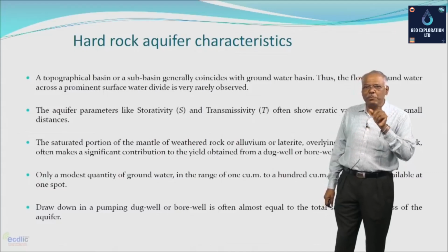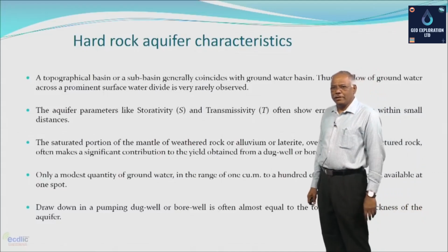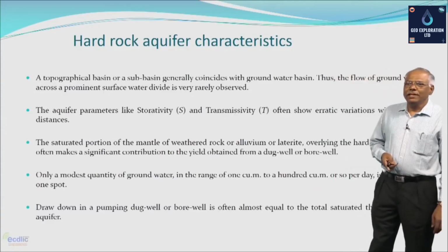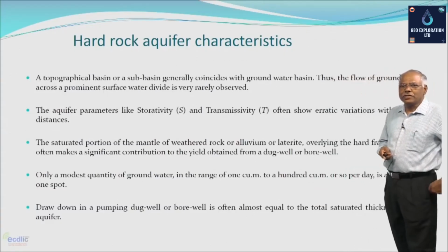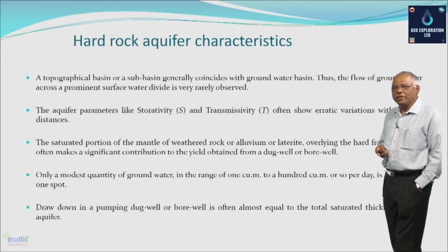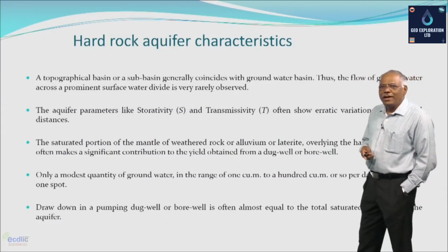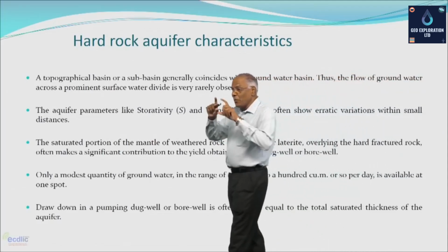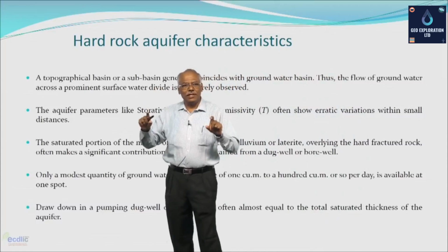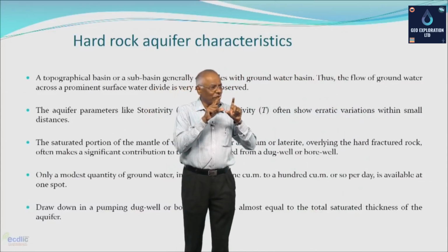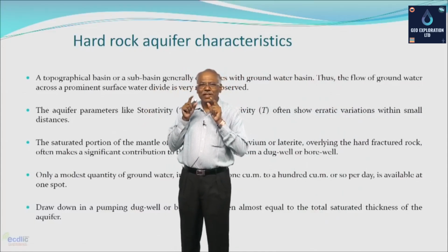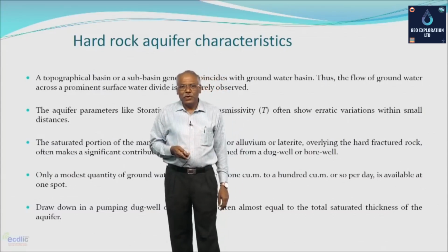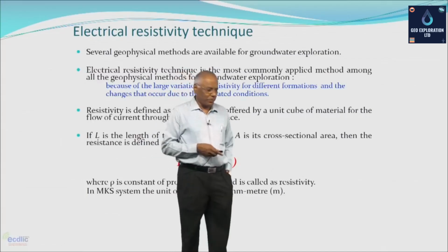Plus, the saturated portion of the weathered mantle or alluvium or laterite overlying the hard rock or fractures often makes a significant contribution to the yield obtained from the dug wells or bore wells. Therefore, the saturated thickness of this particular weathered zone needs to be identified, and that is something one has to look at from the hard rock characteristic point of view.